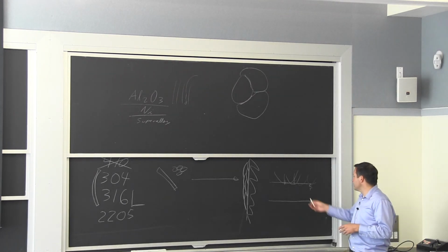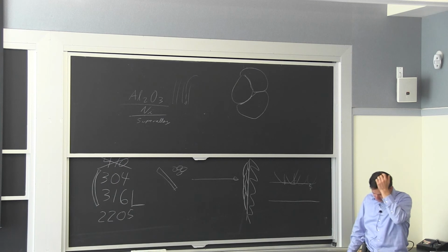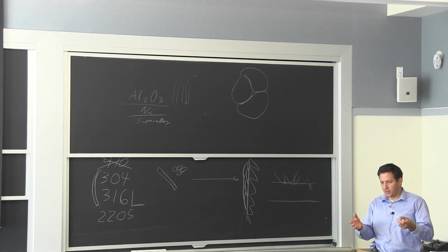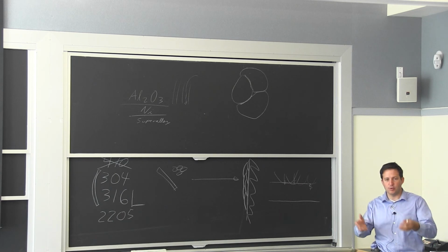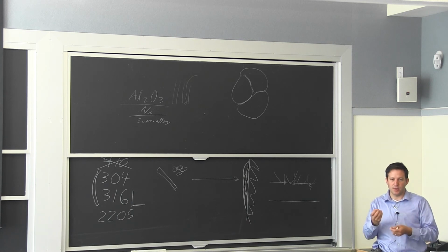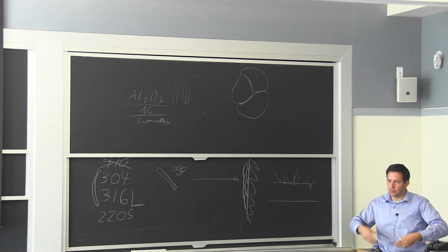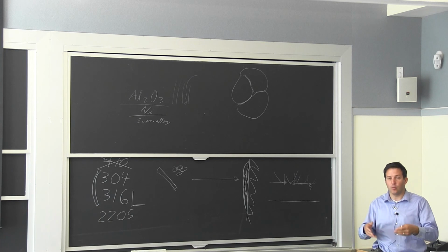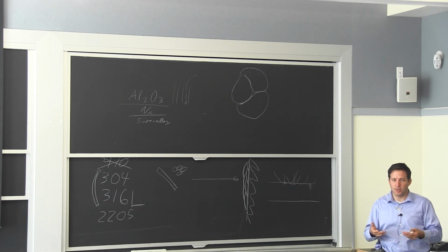There are variations of this that's called mass finishing. In mass finishing, you take the parts and you put them in a slurry, and you kind of grind them or sand them in the process. So the slurry is the particle that creates the adhesion, and you create enough movement that you're eroding away, or you're abrading away the surface, and you finish it.